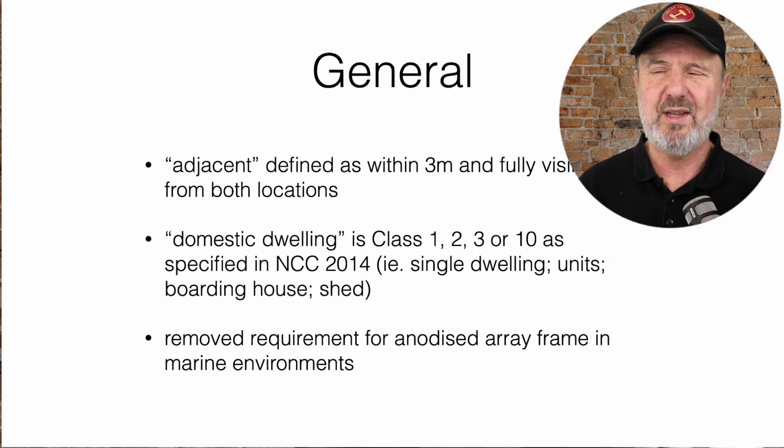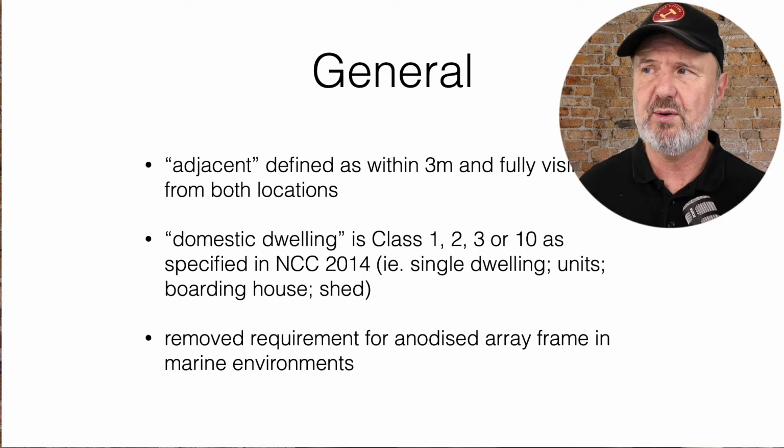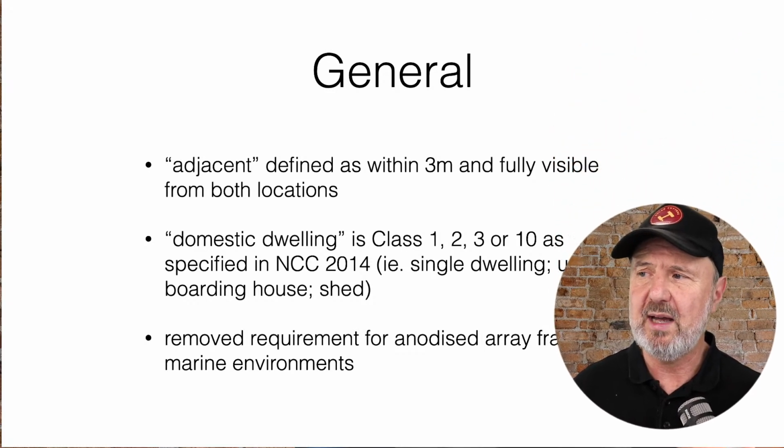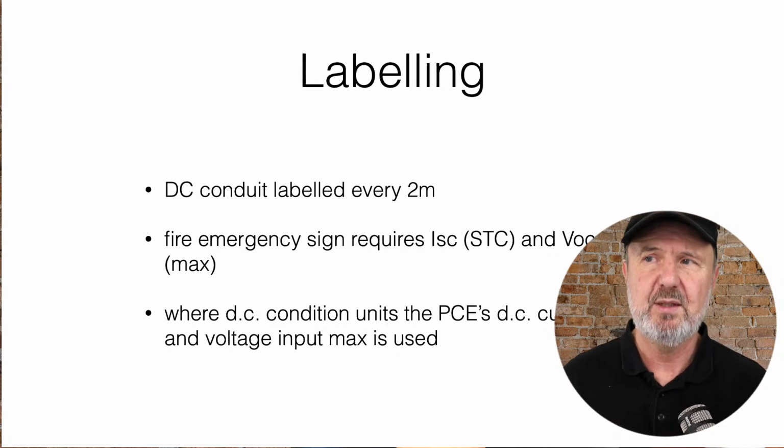We removed one little anomaly, which was requiring anodized array frames in marine environments. You just have to follow manufacturer's requirements. So if the modules or frame aren't suitable for being close to the sea, then you can't use them.